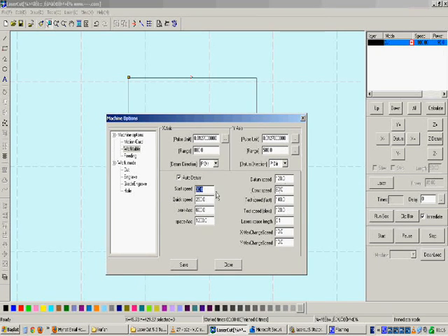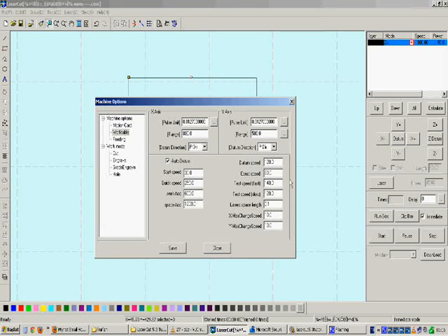You can increase these values with a relation between them. Our past experience shows that giving a start speed such as 30, giving 2 times that speed to the constant speed such as 60, and giving a higher value than the constant speed to the cut speed is a good way. This is very important.